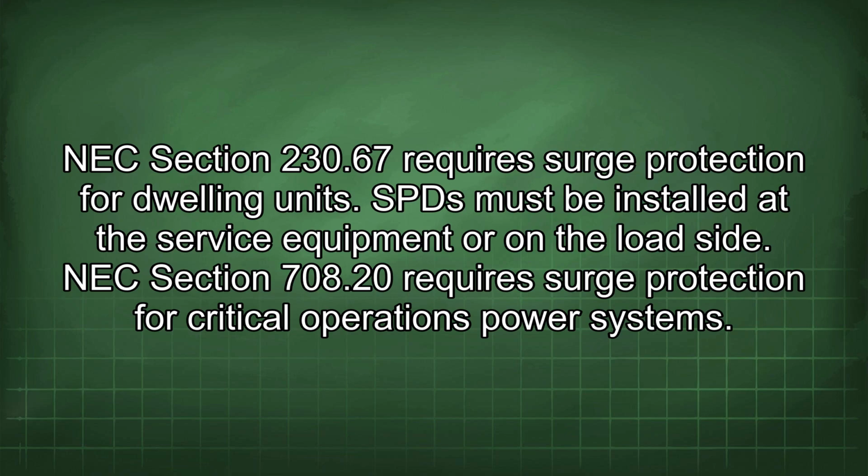NEC Section 230.67 requires surge protection for dwelling units. SPD must be installed at the service equipment or on the load side.